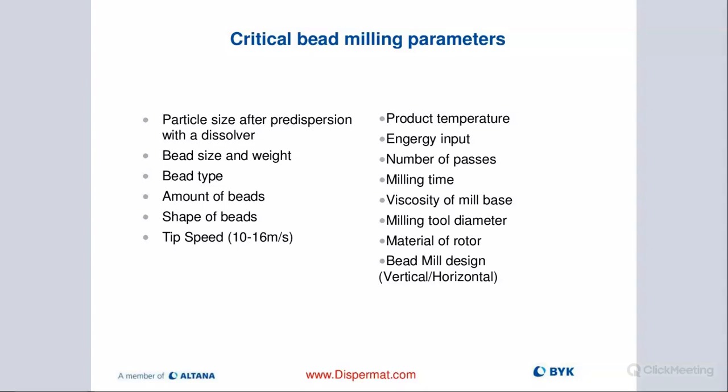The milling time. There is not really a number we can put on that. It's really product and volume dependent. And also, of course, what is my final particle size or particle size distribution? The smaller I want to go, the more milling time I need to add. So we have, for example, some products that we milled with a basket mill in 45 minutes, and we were able to get to about a 2 or a 1 on a Hegman.